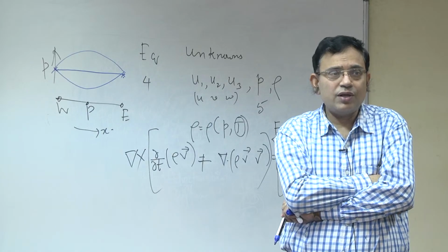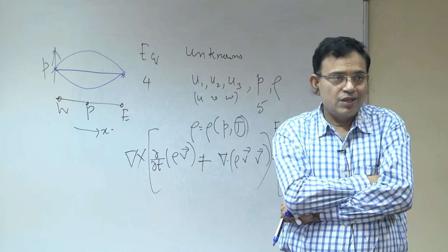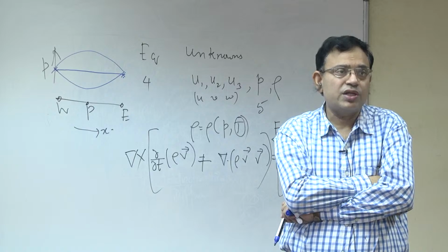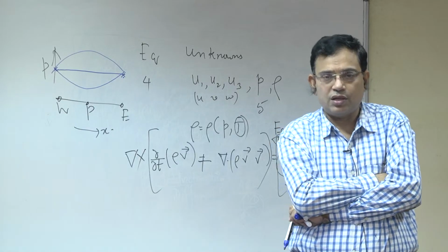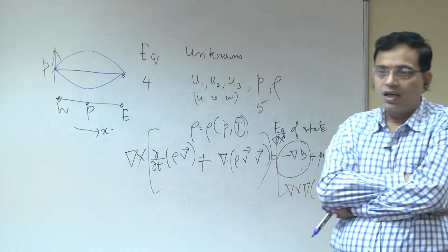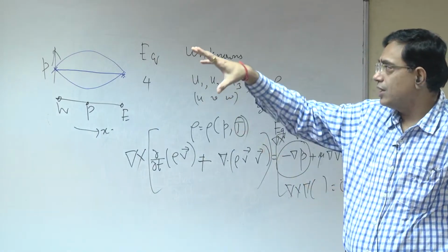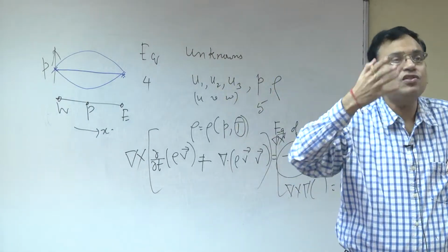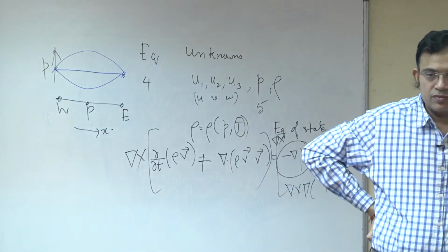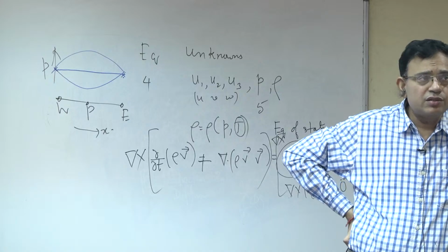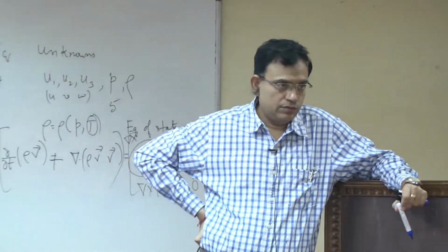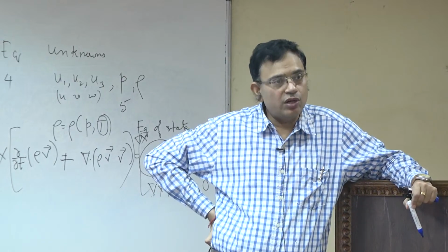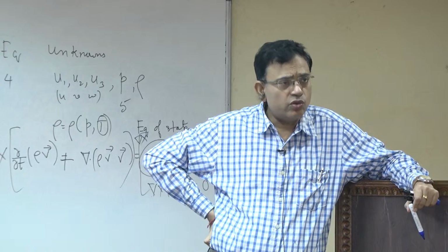But with the advancement of geometric modeling, now the method can take any different shapes like triangular or any other forms of the control volumes, and they need not be so well structured in a stencil like i, j. So, that is called an unstructured grid or unstructured mesh. If it is an unstructured grid, this staggering has no meaning, right. So, then it is better to have calculation at the same point, and that is why collocated grid is used for that.